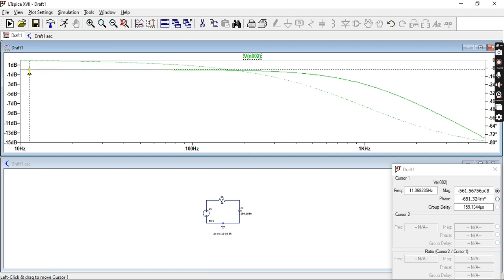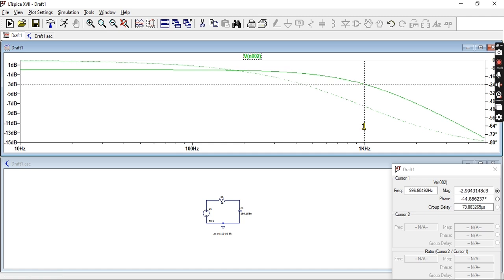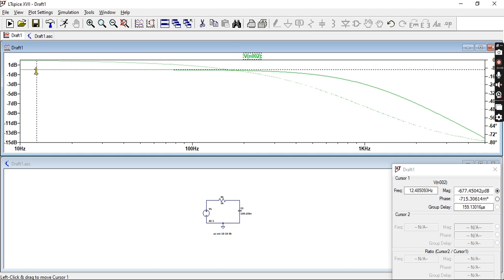So at this point, as I mentioned with regards to filters, if you are interested, please follow along. Any frequency which is below 1 kilohertz will essentially maintain its amplitude. So if you have a sinusoid, it will stay the same if you pass it through this circuit that we have here.